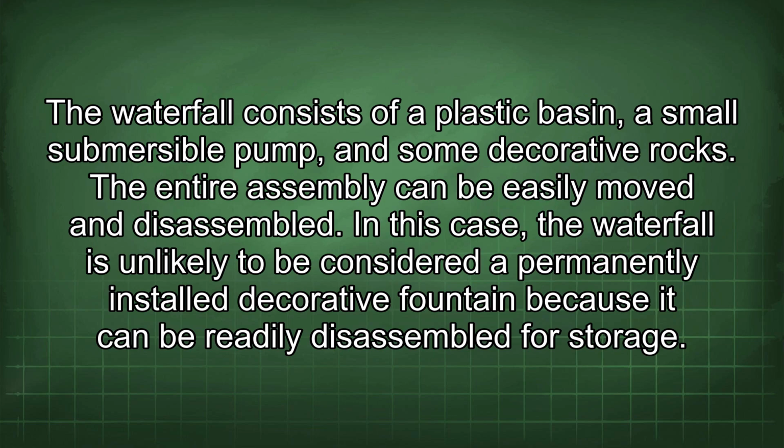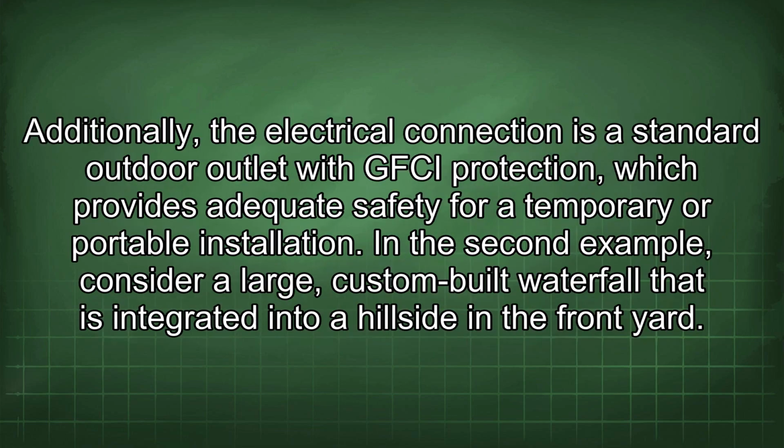In this case, the waterfall is unlikely to be considered a permanently installed decorative fountain because it can be readily disassembled for storage. Additionally, the electrical connection is a standard outdoor outlet with GFCI protection, which provides adequate safety for temporary or portable installation.